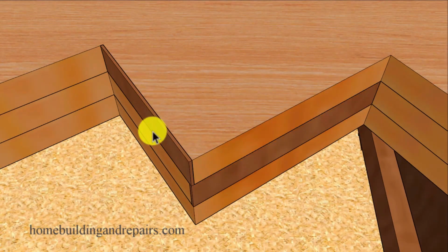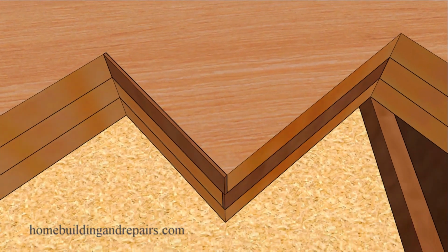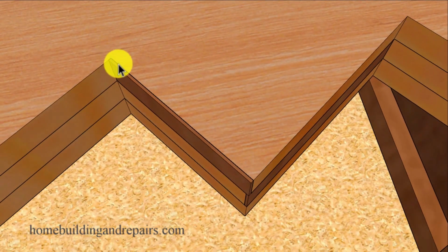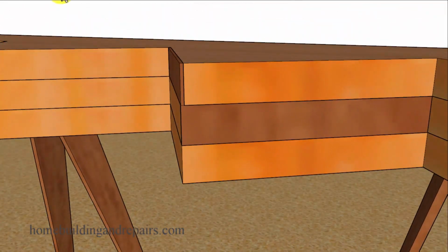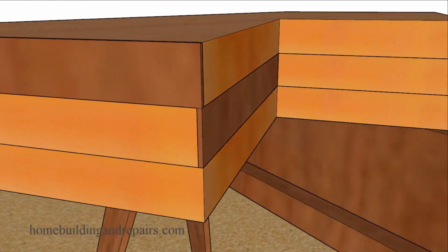And you can do that by adding shims or shaped strips of lumber like we did here. And I would recommend using some type of an adhesive along with some small nails or screws to attach the shim to the stringers. And I will be making a future video to show you what happens if you don't fix this before you install your stair stringers.